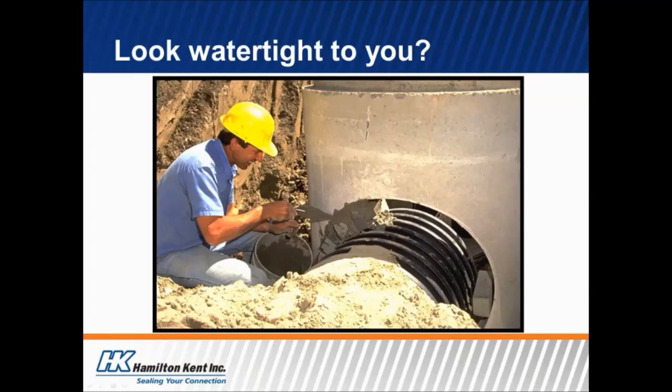And the reason is that we just do not think that this is a very permanent solution. You can see that the pipe going into the structure is going to be a flexible plastic pipe. And if there's any type of differential load put onto that pipe versus onto that manhole, or if there's any type of deflection in that pipe anywhere near that manhole, more than likely that mortar, those blocks that are in there, there's going to be some shifting and likely cracking, and that's just going to create an opportunity for a leak. And while a small leak in a stormwater application may not seem like a big deal, we'll talk about here in a little bit why that could be.